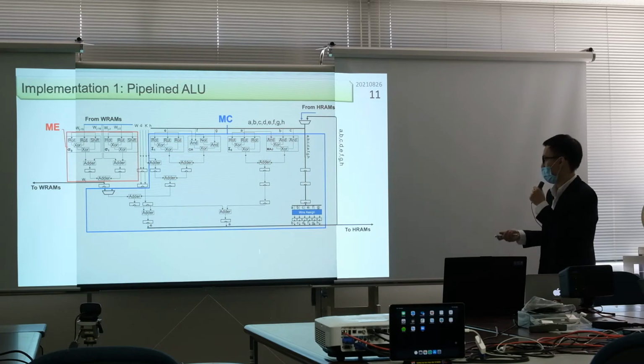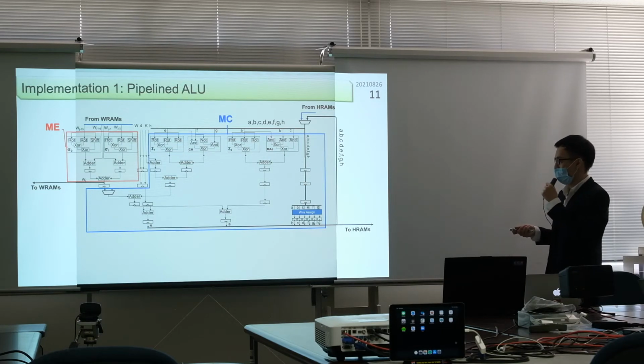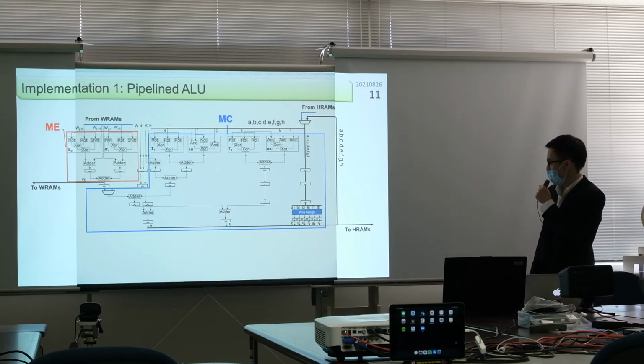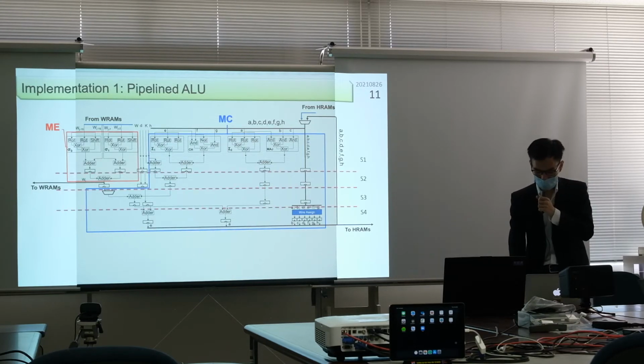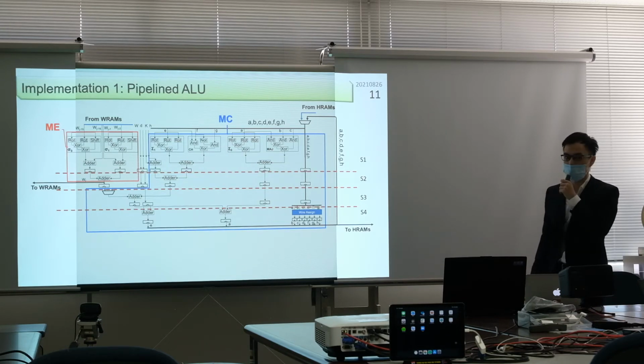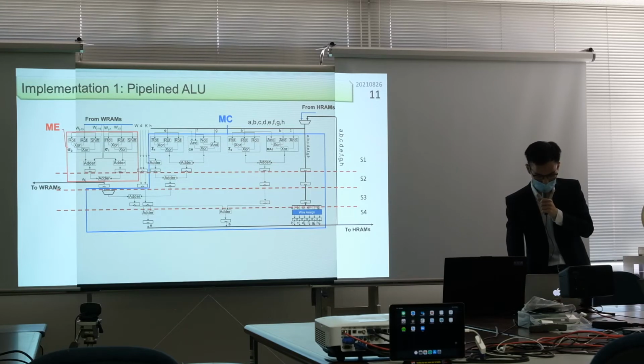And after 4 clocks, the RU finishes one loop, and the result will be fed back to the input to continue computing through the 64 loops. Only the final value will be transferred to the local memory. We designed the RU with 4 parallel stages, so that this RU can compute 4 data in parallel clock cycles.